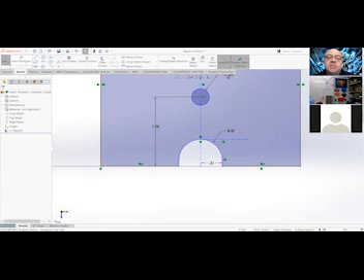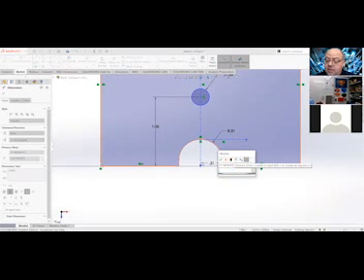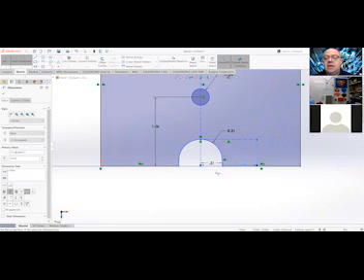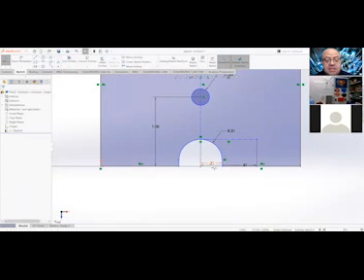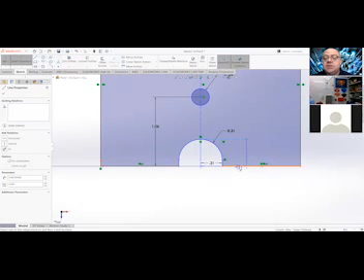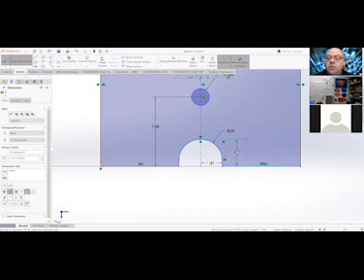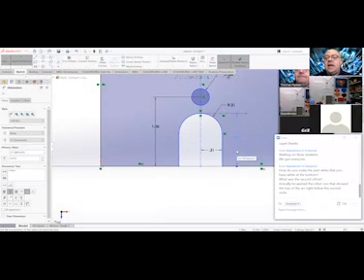And now I'm gonna come in with a smart dimension. And this is just brilliant. Center line, object line, make it 0.81. Well, that didn't do what I wanted, I got the wrong line. I apologize, I did that wrong. I hit the wrong line. Center line, smart dimension line to object line. I got the dimension line, 0.81. Now it's perfect. I don't have to do the offset.